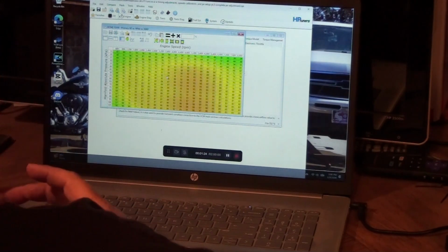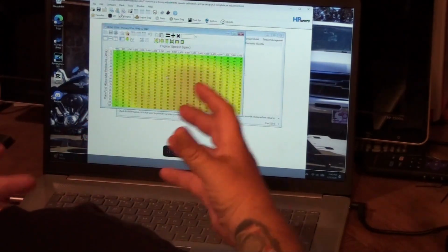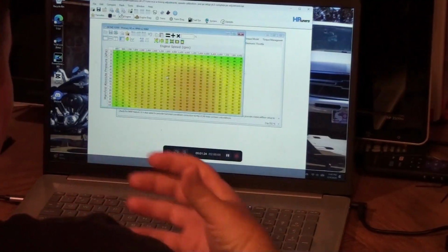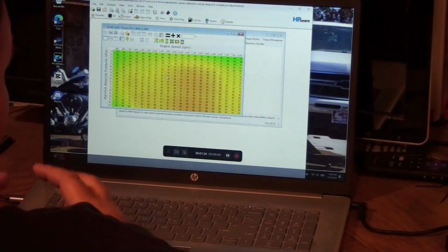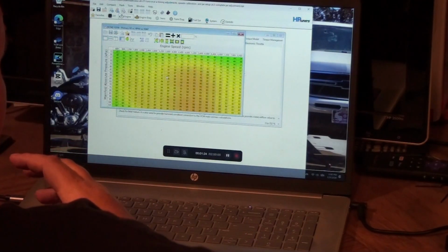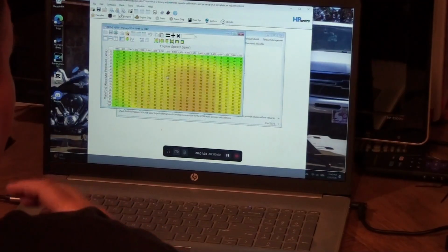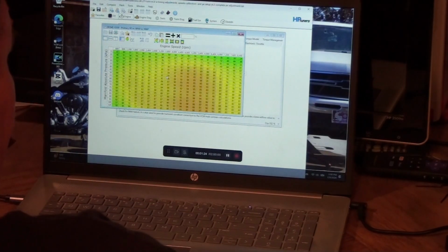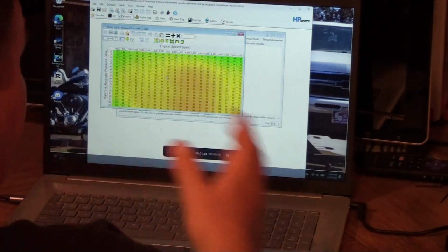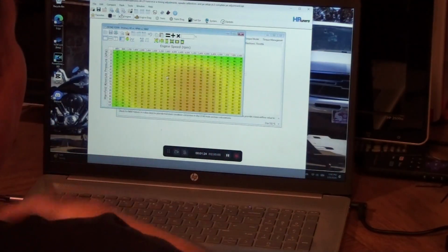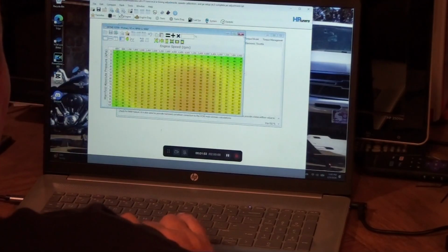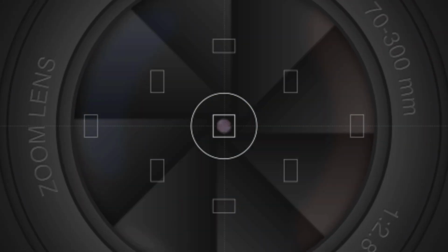Okay, our MAF sensor and our MAF curve tell our engine how much air is coming into the motor to calculate fuel. Our VE, our volumetric efficiency, is telling our engine how full of air it is. So at 100%, it's 100% full of air. Yes, fuel's figured into that. And if it's at 80%, it's 80% full of air.